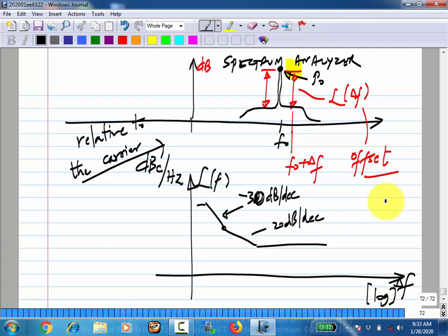No, I mean, it can be due to anything, but finally this random phase noise is due to thermal noise. The thermal noise will always be there. You can try to minimize flicker noise, do whatever, but the thermal noise is fundamental. The only way to reduce it is by increasing the power dissipation. The same type of fundamental relationships you see for phase noise or the circuit noise.